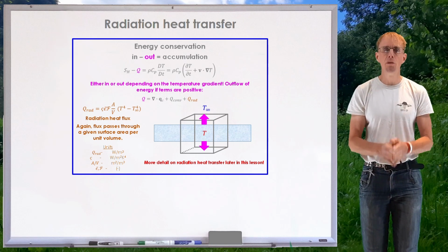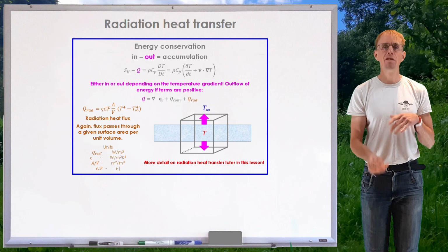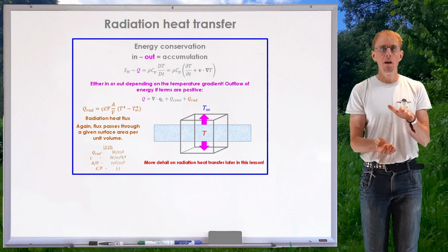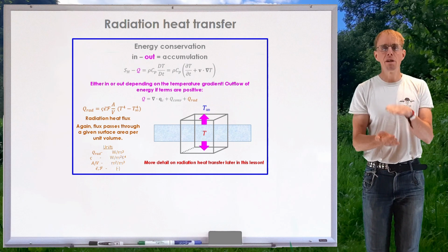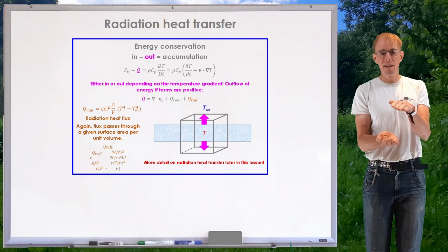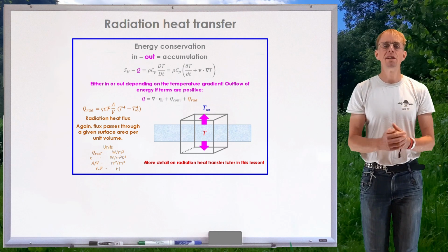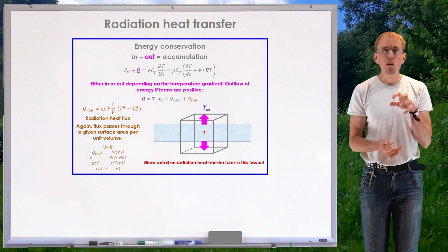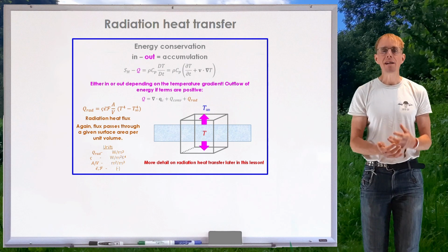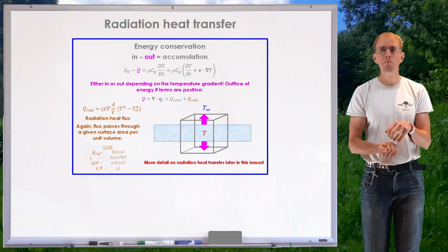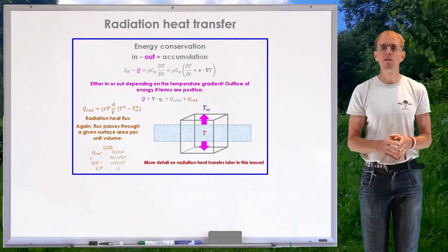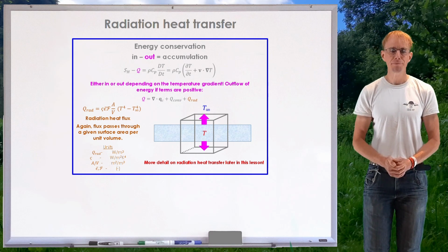And so what we're going to do in this part of this lesson is to look at both of these instances where we can take into account radiation heat transfer as effectively another heat flux at a surface, but also where radiation heat transfer is a volumetric heat source by nature of the fact that it penetrates into the medium, because the medium is what we term semi-translucent.